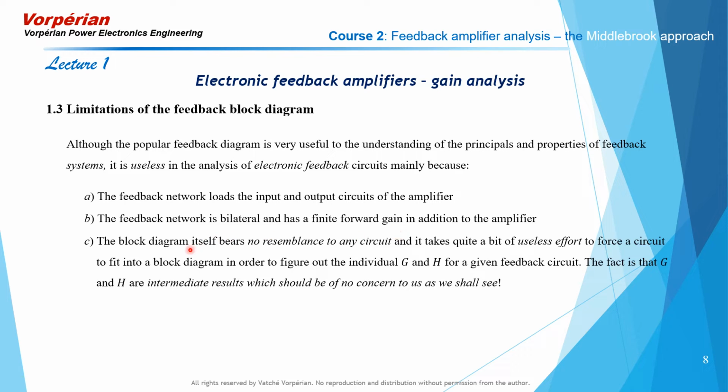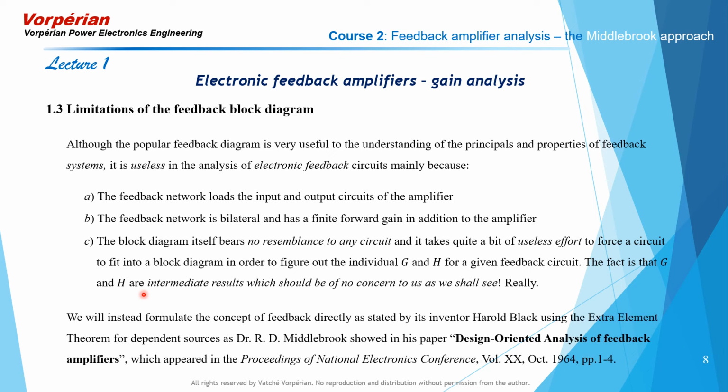Third, block diagrams in general bear no resemblance to any circuit, and the feedback block diagram is no exception to that. It takes quite a bit of useless effort to force a feedback circuit into the feedback block diagram in order to figure out the individual gains G and H. The fact is that G and H are intermediate results which should be of no concern to us at all. Really, I mean it.